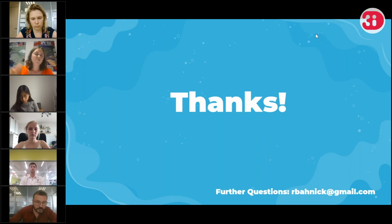Even when I ran the model for as long as 2 weeks, there still wasn't any significant influence by infiltration. I didn't increase infiltration over time. I just kept it at my initial inputs. So maybe if this was in a place with more drainage ability, instead of just having to pump out the water, you would see this recovery happen without having to assume a linear recovery with constant pumping rates.